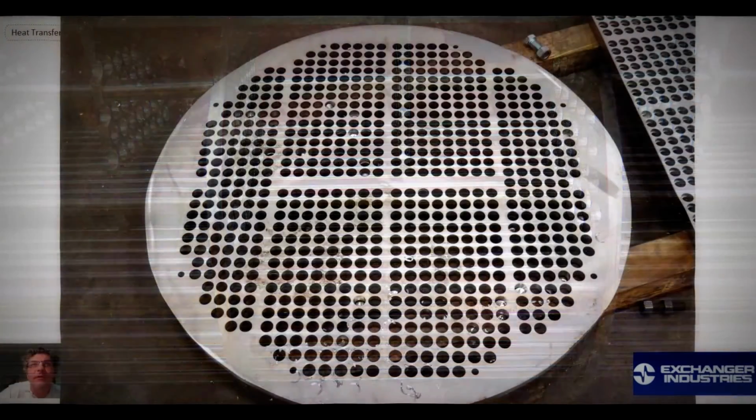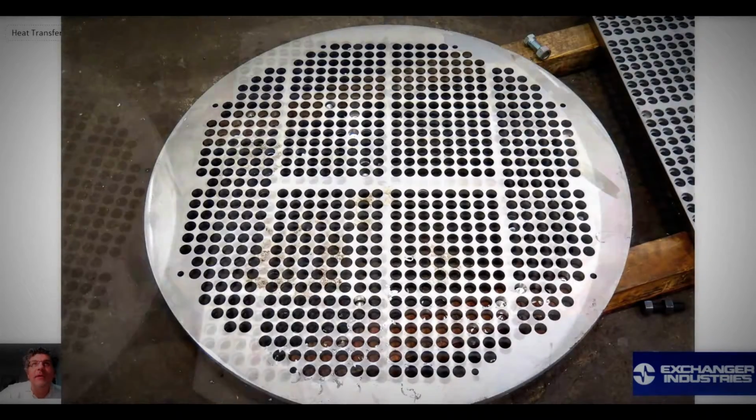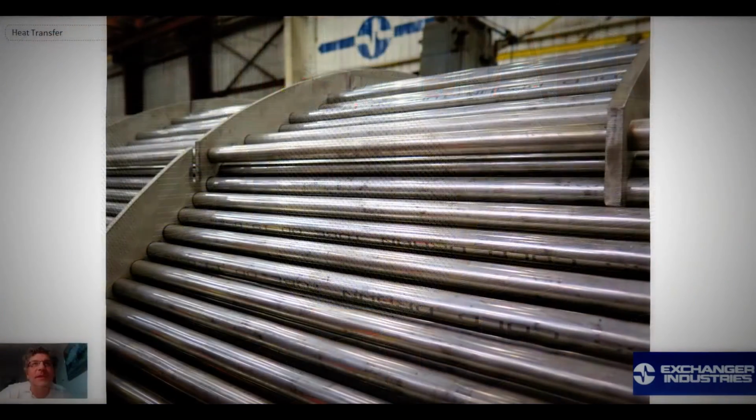And then at the end there are tube sheets. So there is the tube sheet, and there is a baffle. The baffles are partially cut for the fluid to go around that is within the shell. And there you can see all the tubes together with the baffles and the tube sheet at the end.